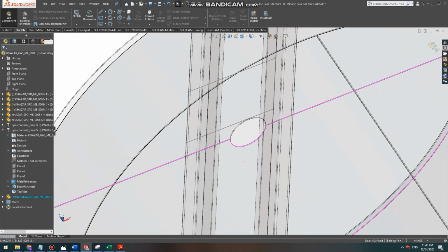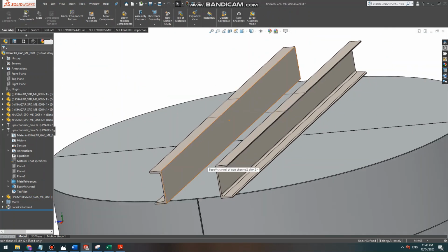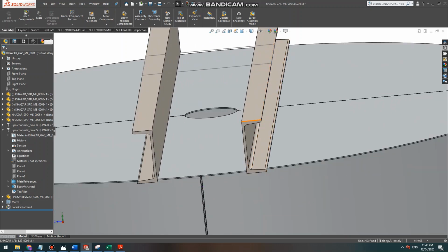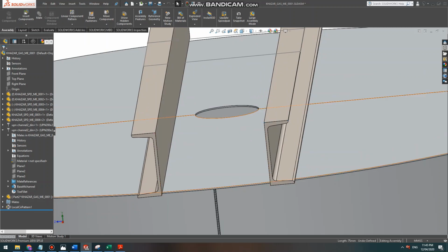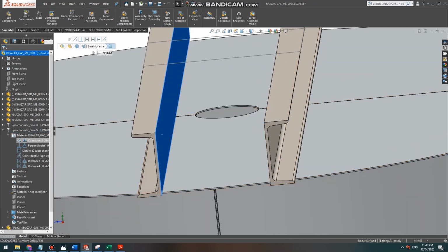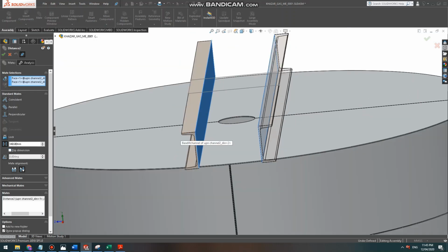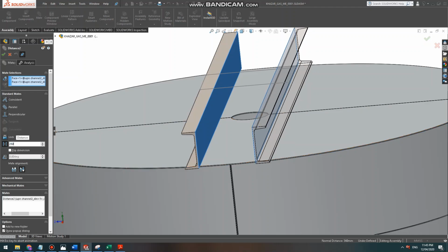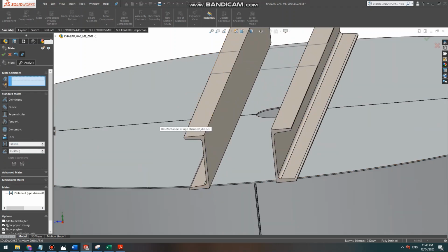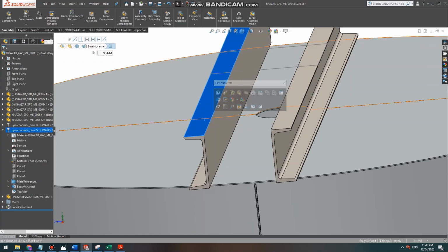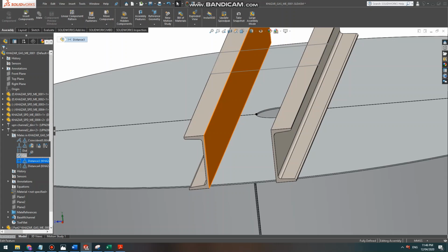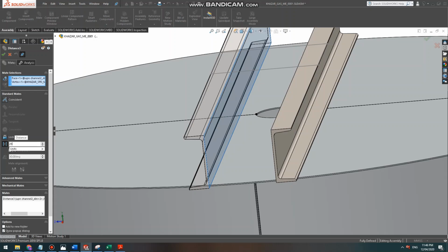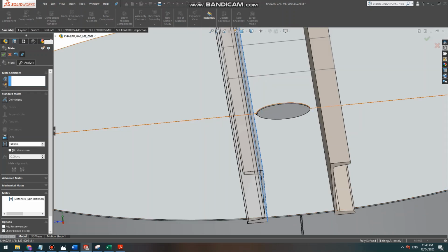Something went wrong, so we have to fix this issue before continuing further, and that thing we can do easily by calculating. So it's 70% 150. We go to this one and we go to its mates, and yeah, the distance between these two has to be not 340 but 250. And yes, after that there is another mate here, which is this one, and for this mate we have to do not 60 but 25, I guess, and I'm excellently right.